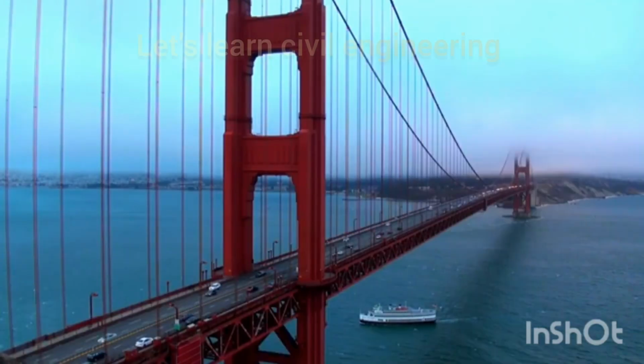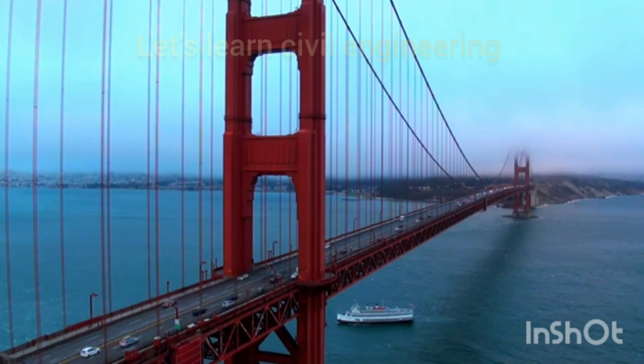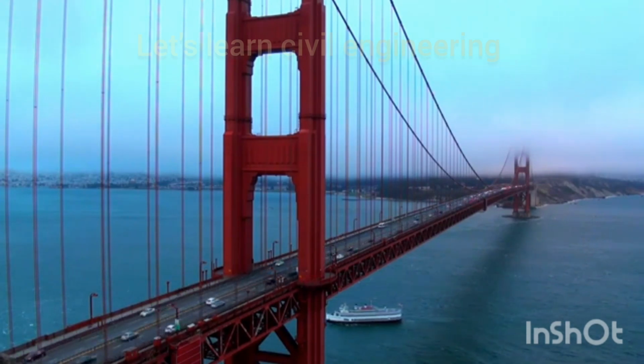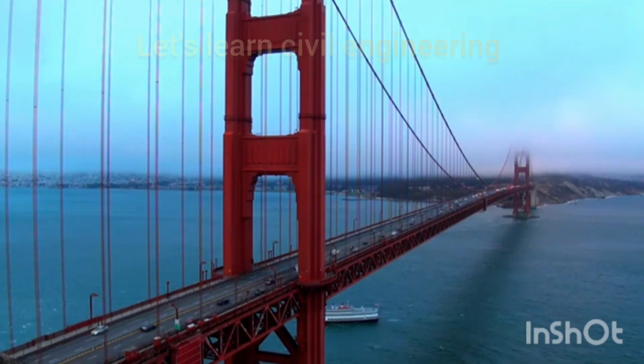Suspension bridge. Suspension bridges are good for very long spans. The basic structural components of a suspension bridge system include stiffening girders, main cables, main towers, and anchorages. Stiffening truss girders are longitudinal structures that support and distribute moving vehicle loads, act as chords for the lateral system, and secure the aerodynamic stability of the structure.